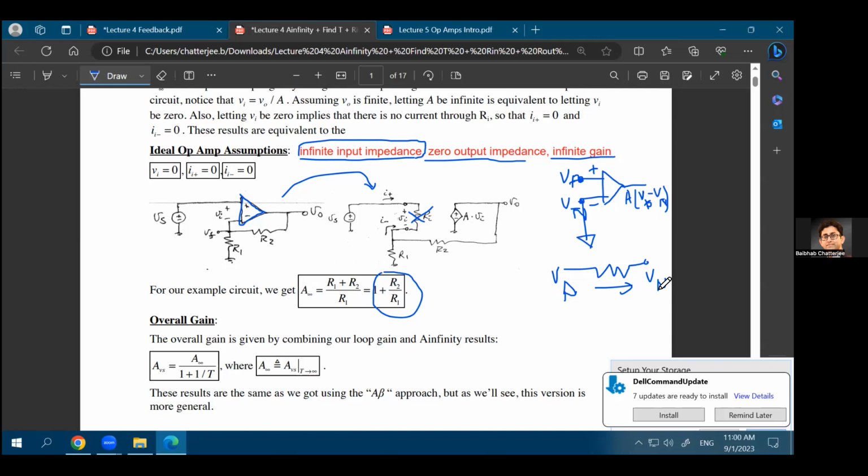Yes, question. When you say that the AC fluctuations are equal to 0, does that mean the average value is 0? Great question. It still means that there could be a DC. The average AC is 0. I didn't say the average DC is 0. The DC point could be, let's say, at 500 millivolts. But it could be a fixed DC point, and that's what biasing means.